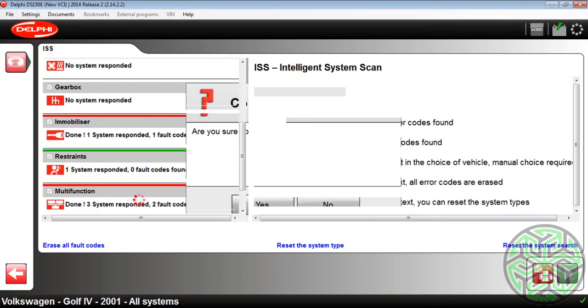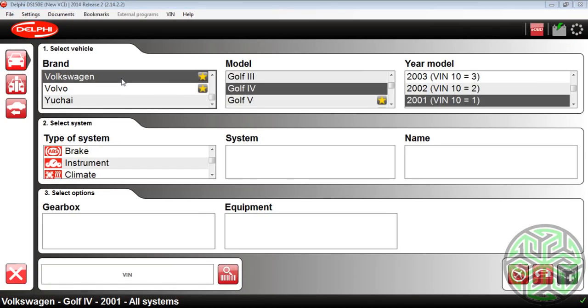Okay, so we are basically done. We've gone through all the basic functions and features of what the software can do: read fault codes, erase fault codes. We can get our real-time data list, customize the real-time data list. Check out all our measure value blocks, see what's happening while the engine's running. Good for doing comparisons and anything else before, between, or after working on the engine. Make sure everything's 100% sound instead of finding out the hard way.